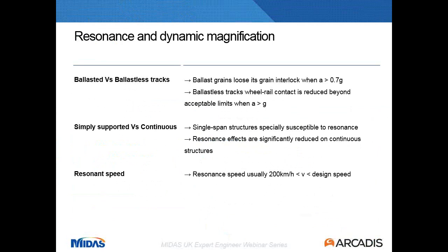But if you're using ballastless tracks, you don't have this problem with the ballast, obviously. But when the acceleration exceeds the gravity acceleration, then the contact between the wheel and the rail is lost. And that also leads to a very quick deterioration of the track and as well to the risk of derailment.